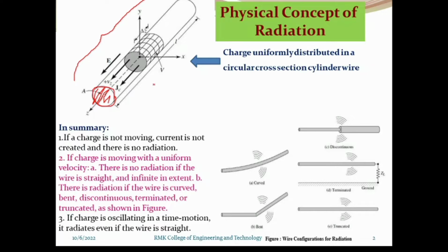For this conductor I am going to apply electricity with a DC voltage. You know that with DC voltage we don't have any frequency; DC has zero frequency. So we pass this DC signal here, and the charge carriers will move around this area A. They will pass towards the core. If you pass a DC signal, all the charges will occupy the center area and move with uniform velocity, and in uniform velocity there is no escaping of any charges towards the outer side.